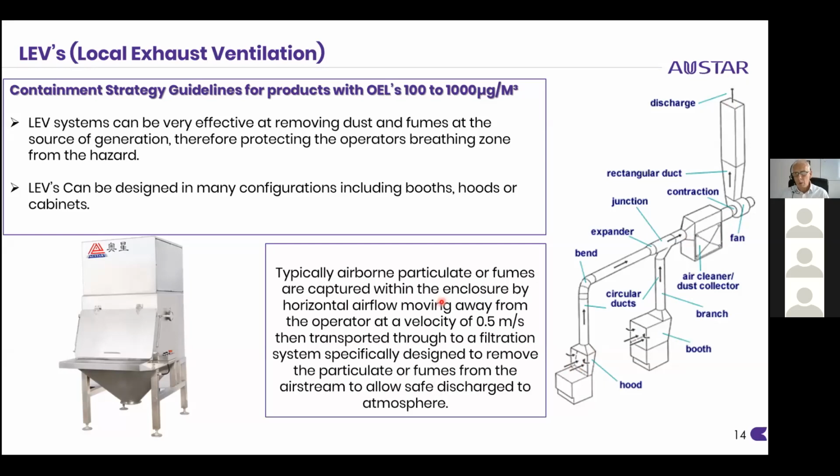And how does that work? When we are dispensing or tipping, the airflow is such that any particulate that becomes airborne during that process will be exhausted away into the system, taken away through the filtration, and as I say, exhausted. So it takes everything away at source, transports it to the filtration system, removes it in the filtration system, and then takes the exhaust air out of the building.